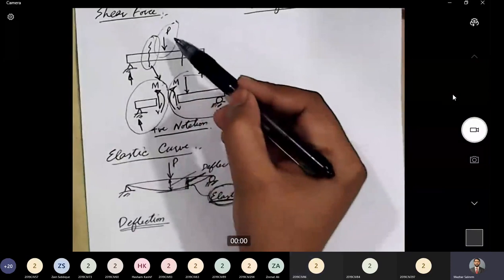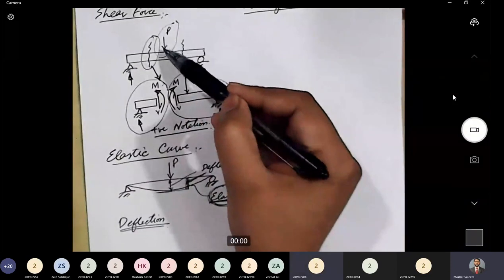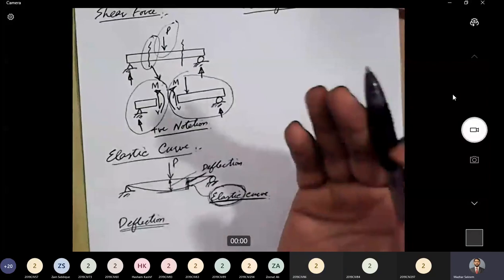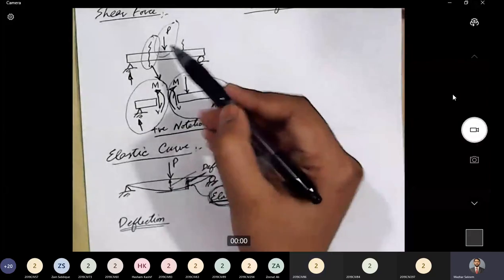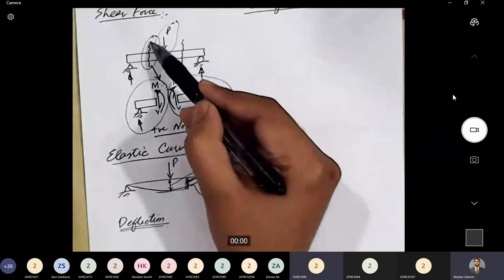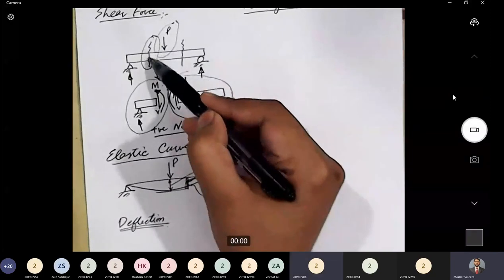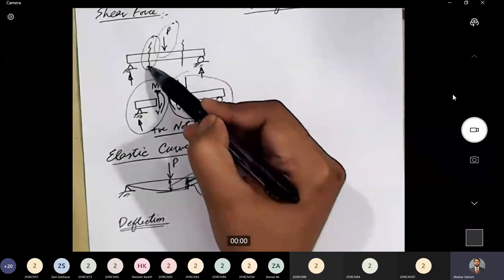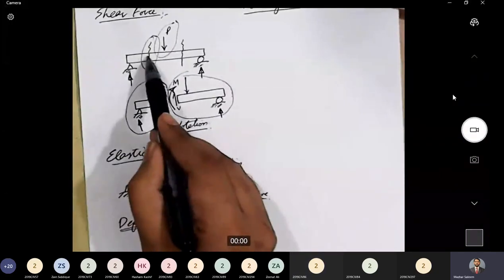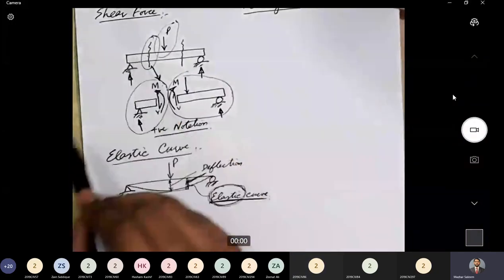It depends upon the given problem. There may be 1, 2, 10 or 1,000 different applied loads. So it depends upon the applied load. In this case, the load was acting only at this point, and I wanted to consider shear force at this section, so I have cut the details of this section here. Is there any external load applied on the left side of this section?